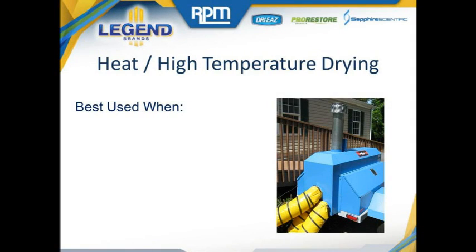Finally, we discuss heat and air exchange drying, otherwise known as heat or high temperature drying. These types of drying systems typically utilize a constant, fresh supply of outdoor air and the addition of heat to create a drying environment. Whenever outdoor air is used, with or without heat, it's important to ensure that the outdoor air is drier than what can be created using the mechanical dehumidifiers we've just discussed.